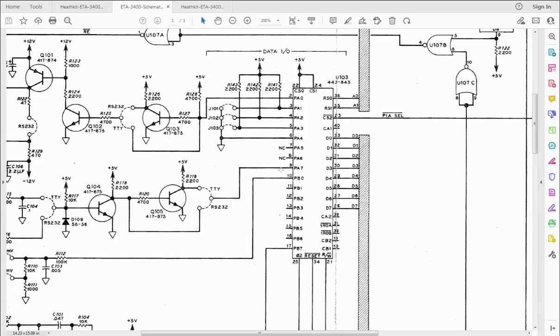And then it pretty much applies the same timing that it applied when creating a transmit stream and assembles an incoming byte. Well, actually, this doesn't. This just passes this bit on to the processor, and this bit is set by a bit from the processor. So it's done in software.